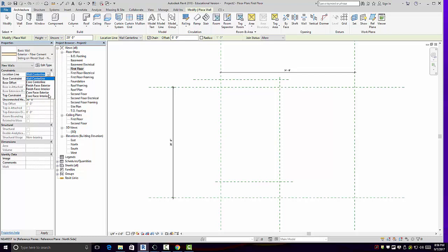So when we lay this wall out on the 34 feet, that dimension of 34 feet actually goes to the face of the stud. Carpenters here? You do carpentry? You do everything. Yeah, okay. So you know it's to the rough, right? So we're dimensioning to the rough. We're going to draw this wall based upon the rough. So the actual width of the house is going to be just slightly more than 34 feet.